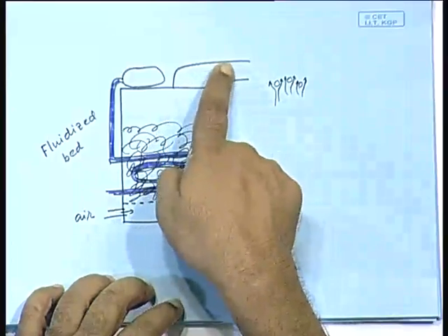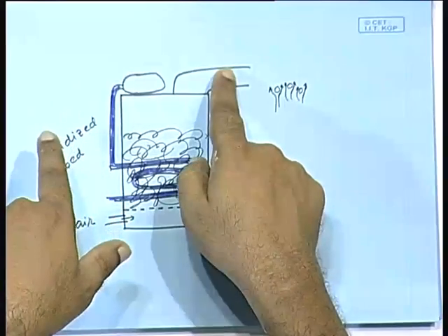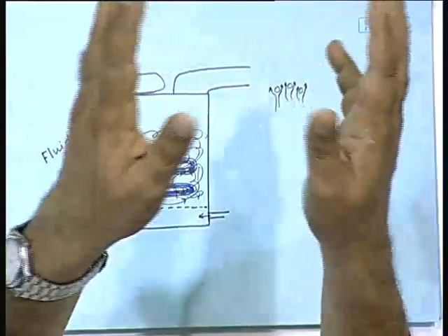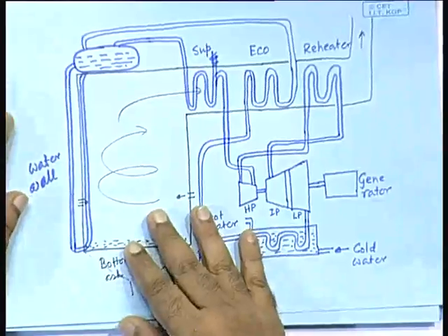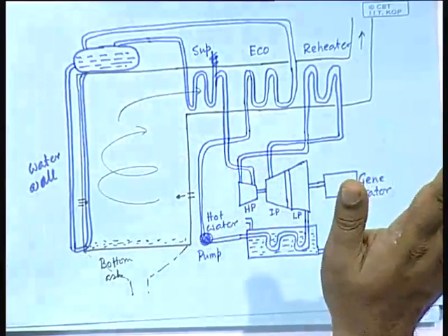If you have incomplete burning, you have production of producer gas. So that will happen here. So as a result, what will go out of this is hot, but at the same time it is also fuel. If at that stage you have the electrostatic precipitator and whatever small amount of coal particles are there, if you can take it out, it again becomes a clean gaseous fuel, which you can use in the same type of power plant that uses the gas, a very clean system.